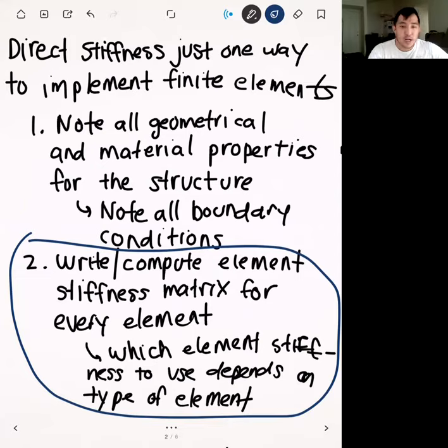But for every type of truss, and for beams, and for frames, every type of element has their own equation that governs their behavior, and you can think of the element stiffness matrix as the matrix manifestation of that. Okay? And what you'll see later on is that this element stiffness is not only a combination of just the equation, but also the type of element that we put on there, the shape of the element, how many nodes are in the element, and stuff like that.